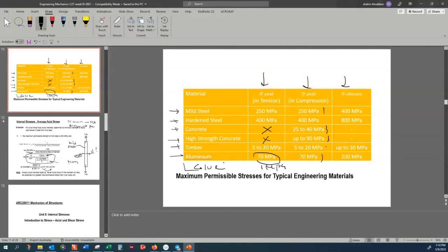It's still much, much less than steel. Even though the glue would develop smaller stress, because the glue is much weaker than the steel, you have to compare them with the reference number. The reference yield value of the steel is 250. The yield standard value of the glue is something like 1 megapascal. So the correct answers by Darcy and Nguyen. Appreciate that.